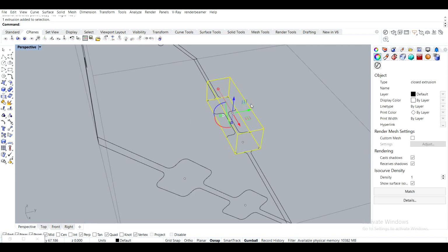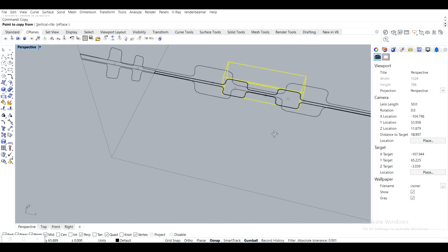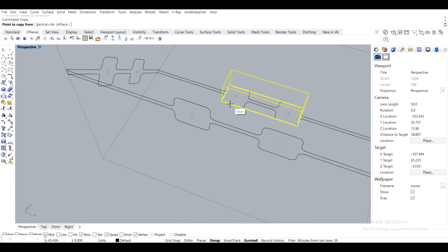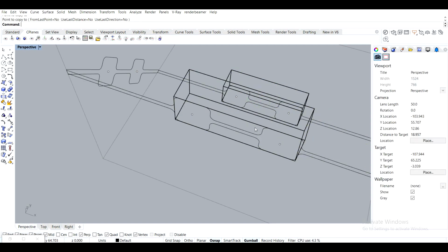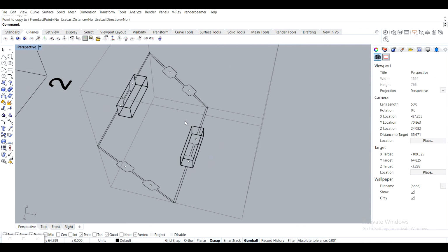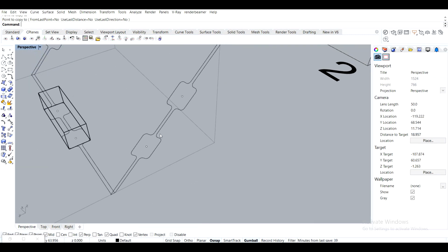Also, it's symmetrical, so I can just take a copy of it, figure out some sort of shared point that I can use, and, yeah, I'll just use a quad, I guess, something like this. Okay, so we have two boxes here, and I need two more boxes. So I'll just start creating a box. I'll choose 3-point box rather than a regular one.